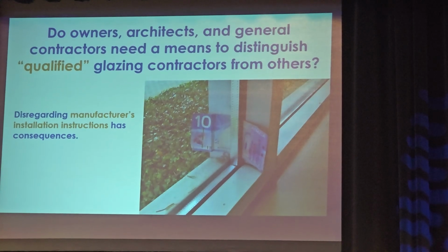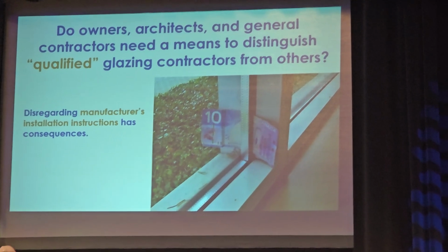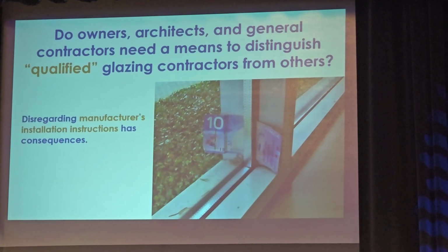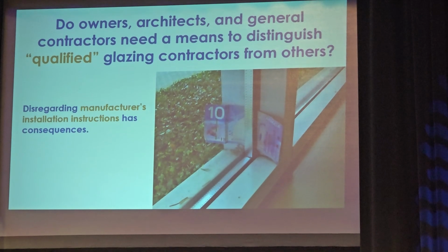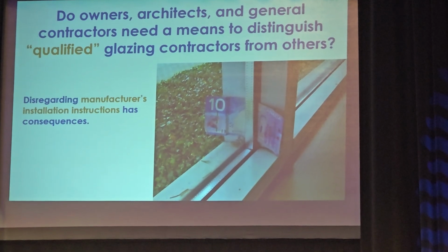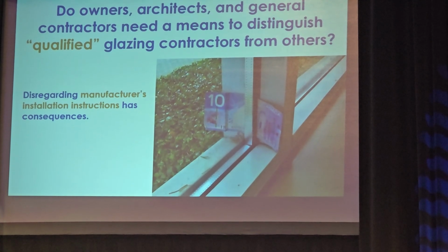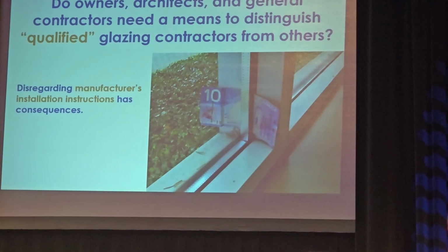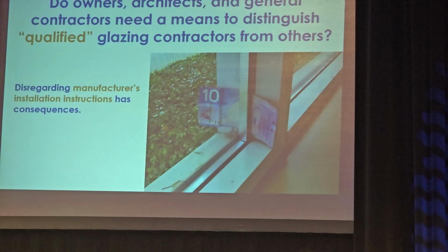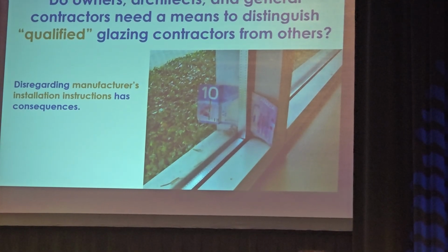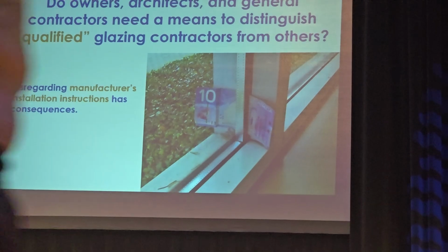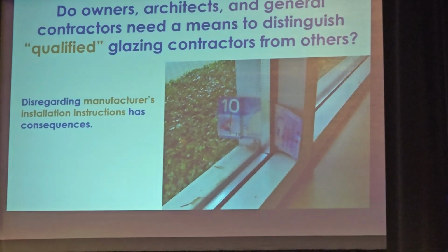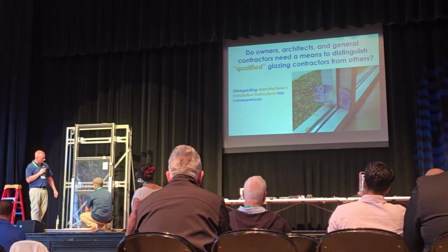Well, for the curtain wall now, there's a formula for all glass manufacturers for different products, where we measure a daylight opening at a certain amount of glass weight that's recommended for each system that you use. So on this curtain wall, as you can see, we have our pressure plate covers, which have a thermal rubber on the end of it that seats against the glass. Once we center this glass up equally on both sides to cover the band, then we apply these pressure plate covers.